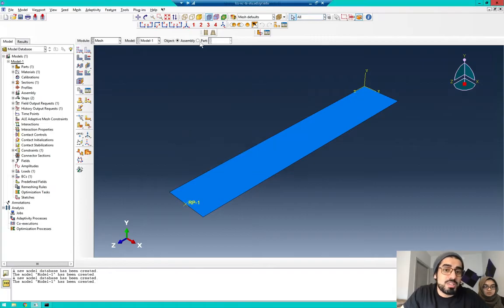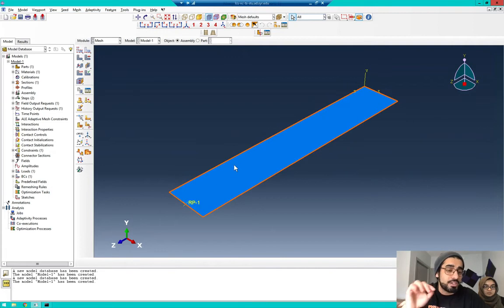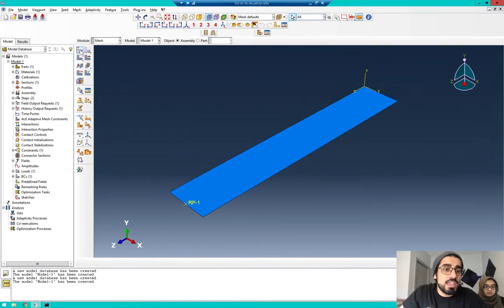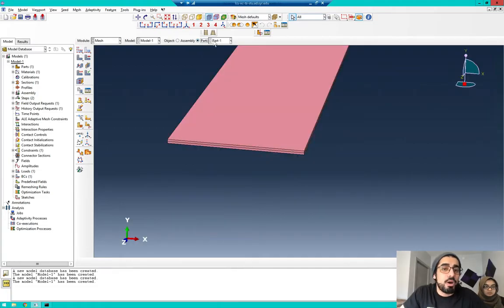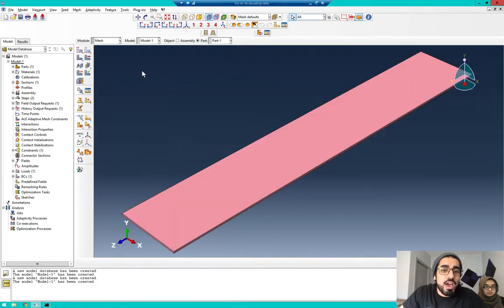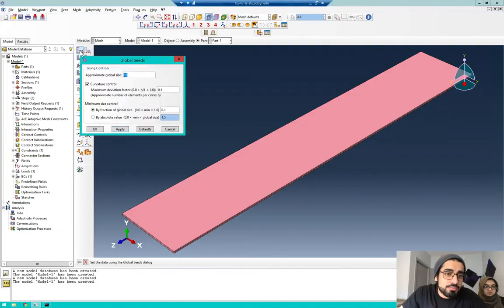You might have this problem because I'm meshing the whole assembly, even though I said that for this part I want to mesh it on the part when you create the part. So I go here, meshing. Before I click on this, I go here, mesh part 1. I see this, and they ask, do you want to have a node every how much? If I keep it at 15, it means every 15 millimeters I'm going to have a node. Easy, right? But no, I want to have a node every 1 millimeter.